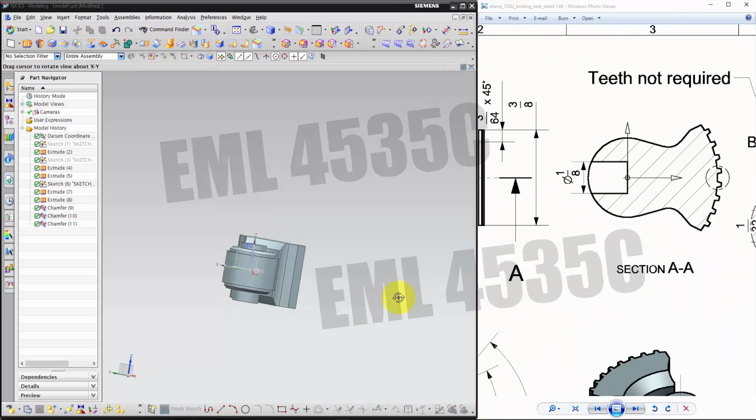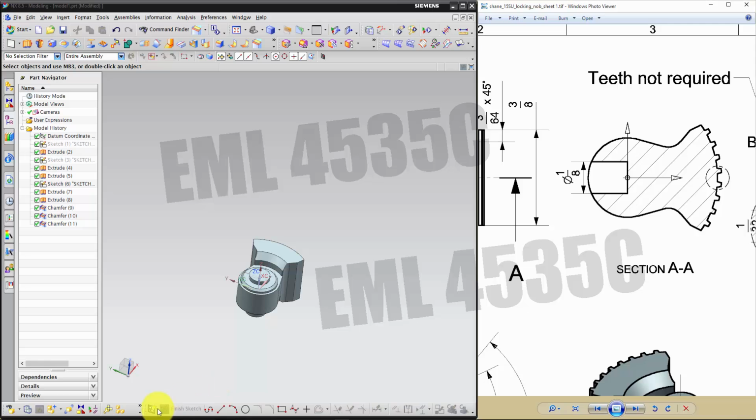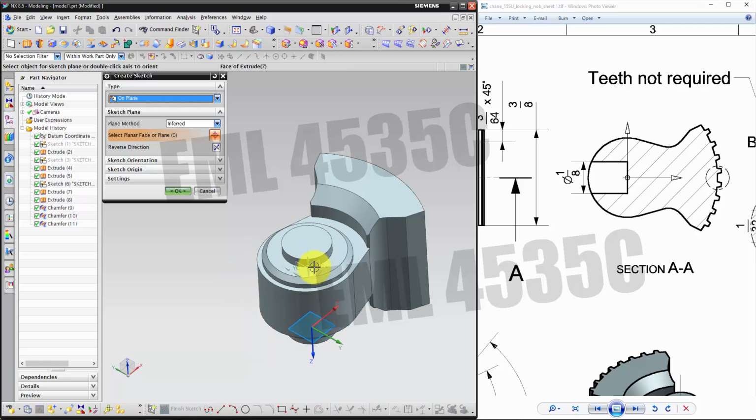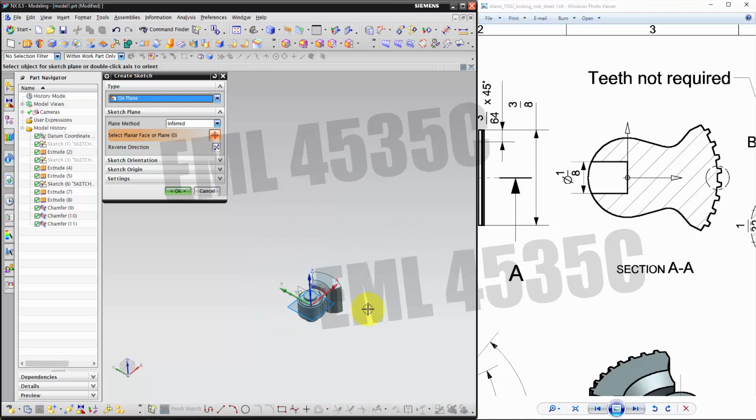It's pretty easy. The only thing might be it's the first time we draw something on another plane, other than XY. So you want to select the YZ plane, which is vertical. It might be hard to select a plane at first. The trick is zoom out, make the datum in the middle become bigger than the part. Then you can click on this corner. Okay.